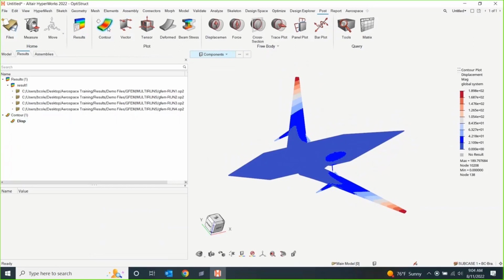Now back to what I was saying, if I wanted to put say a stress plot on this or some other type of coloring, some other contour, I'd be forced to go back and essentially forget this displacement contour. But not anymore. So what we're adding now is this ability, we call these plot controls.